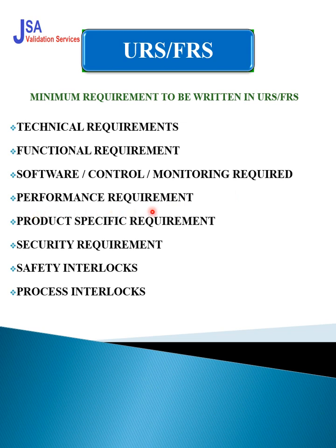Performance requirement: which type of compressed air is required, what's the dew point of compressed air. Okay, product specific requirement: if the compressed air will be directly exposed to the product, what is the product specific requirement? What is the level of moisture you require? Okay, what is the dew point, -60, -40 or -80 you require? Okay, what is the particle count limit? Which class, 0, 1, 2, 3, of compressed air do you require? That should be product specific. If there is any product specific requirement, that should be mentioned.